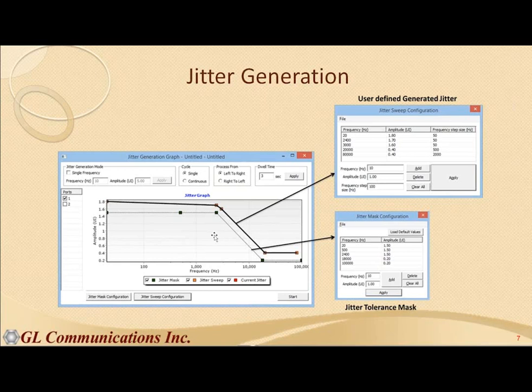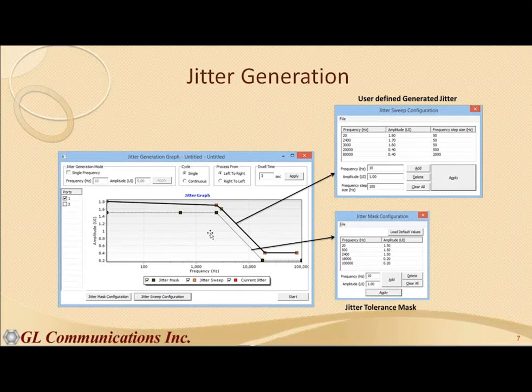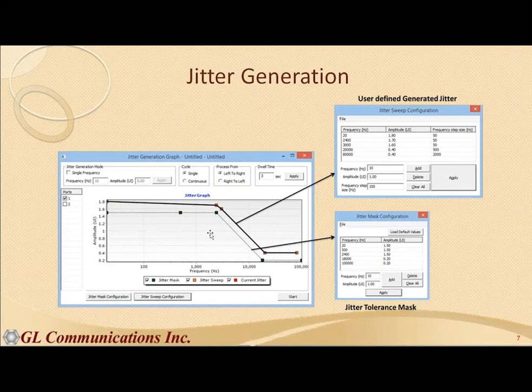That deviation from the ideal can be measured either in time domain or in frequency domain. Obviously, if the ideal instant when the pulse should start is different than when it actually starts, either by plus or minus some few nanoseconds or more, then we call that jitter. And the way that jitter varies as a function of frequency, meaning how jittery it is.